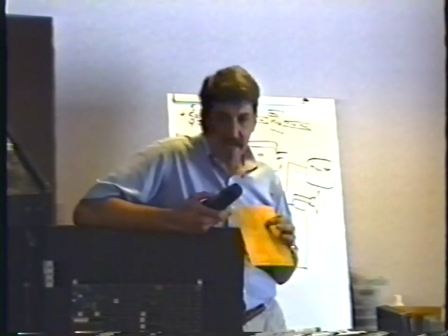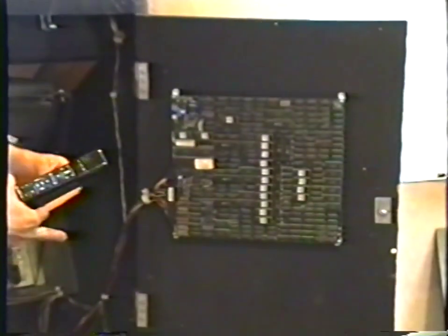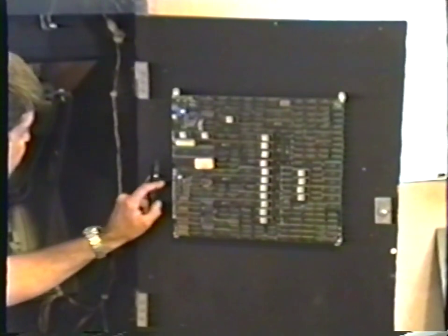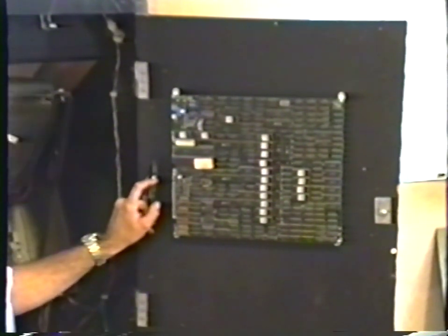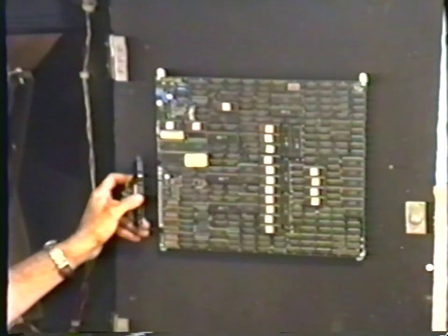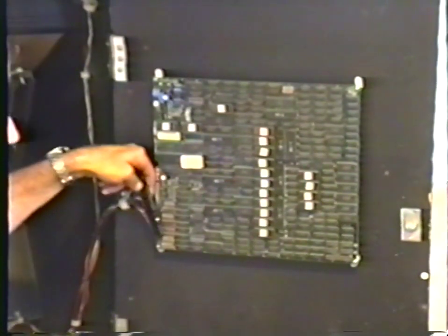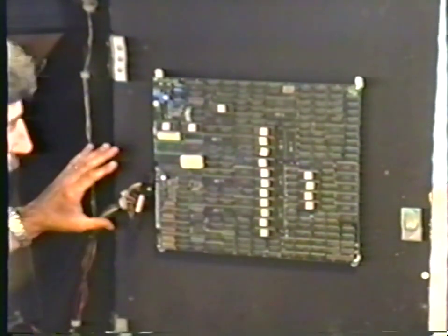And then pin 7 and H is what we call the keyway, and that's a blank spot on the connector. If you look at the connector, you see this little white part right here. This is a keyway, and there's a slot in the board right here. Essentially, it keeps you from plugging this thing in upside down. It idiot-proofs the connector so that you don't run power into the wrong part of the connector.